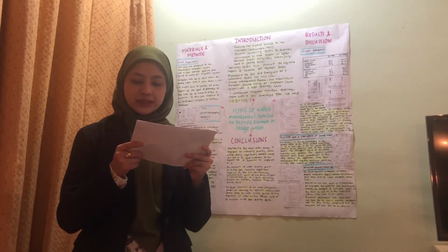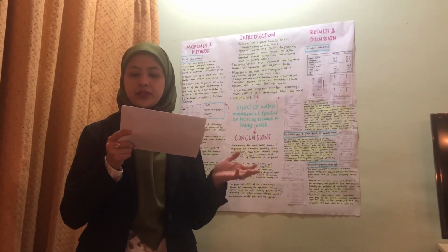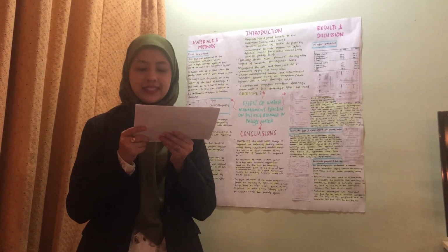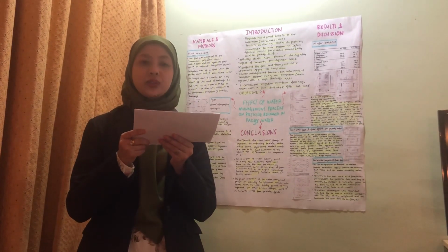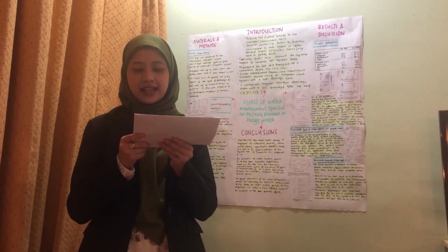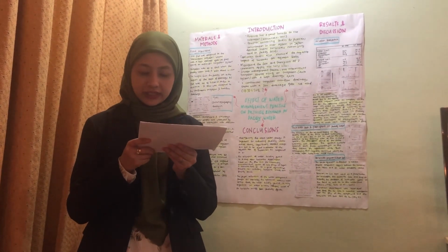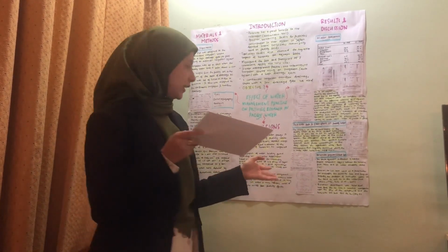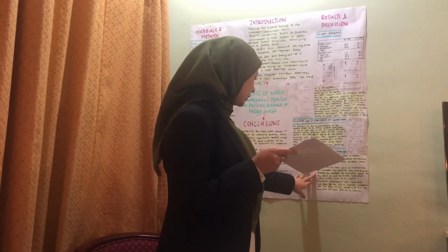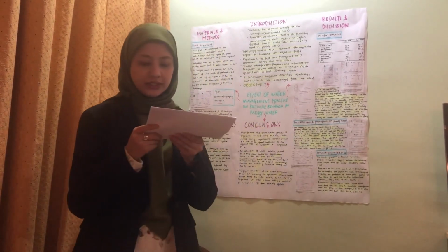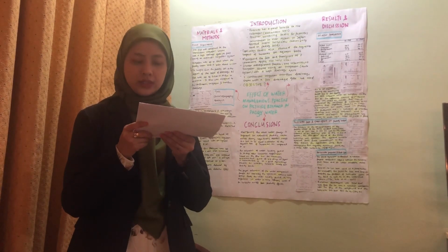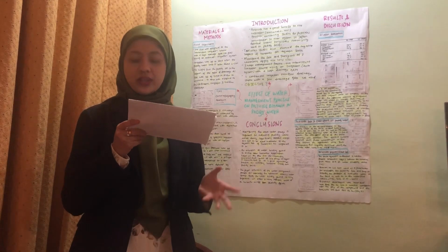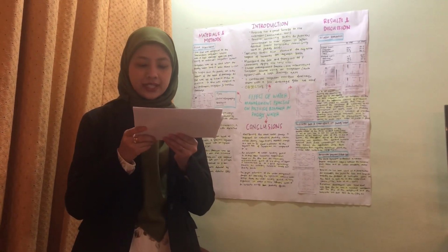The best water management practice which can be recommended for use during the water holding period is the intermittent irrigation scheme using an automatic irrigation system with a higher drainage gate. So the proper extension of the water management practice for obtaining the optimum excess water storage during the water holding period is very important in order to have efficient control of the herbicide runoff from the paddy field.